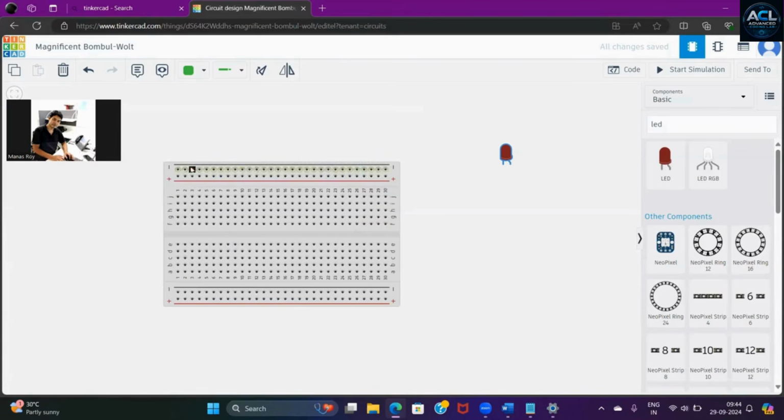So this is the basic concept of a breadboard. And another thing, I told you there are 4 parts of that breadboard. This is one, the part above the red line. Below the red line, there is another one. And here is a gap actually. So there are 4 parts which are not connected. This is the basic concept of a breadboard. Once we practice, we'll come to know more about this.